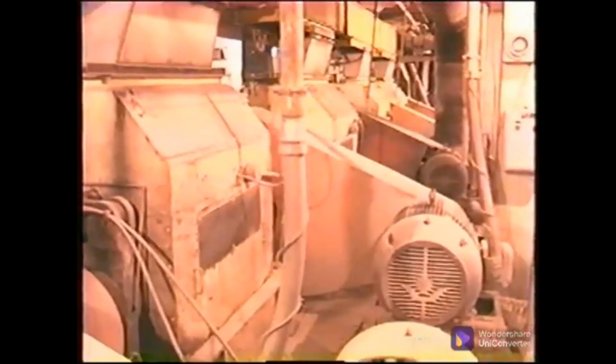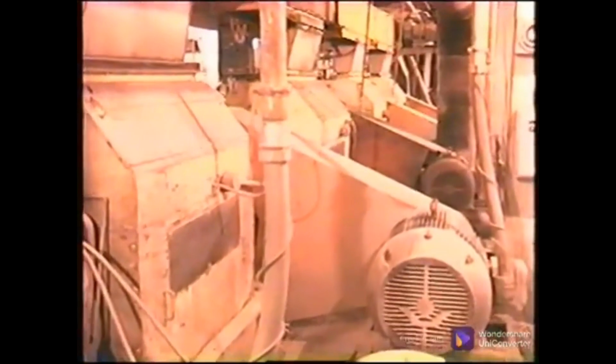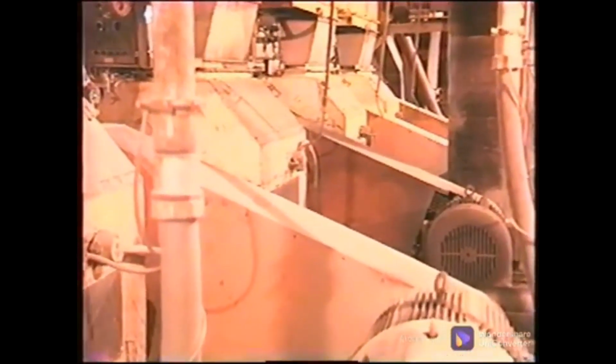Earlier we mentioned that heat is the number one enemy of belts. The belts should not run in applications where their temperature will be over 140 degrees. The cooler the belt runs, the longer will be its useful life. Belt drive guards should be a cage type with plenty of airflow to cool the belts. Solid enclosures trap heat, causing the belts to overheat, shortening the life. One drawback to the banded belts is they tend to run hotter because the band traps the heat, not letting it dissipate.